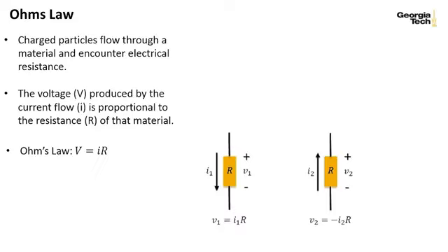So if we have two electrical devices, one with a current I1 flowing from plus to minus V1, then we have V1 equals plus I1R. If you consider the other device, V2, where we have current flowing from minus to plus, V2 equals minus I2R. So the same mnemonic device that we've used all along: whichever sign for the voltage you get to first, you can use that one in your calculation. For V1, the current gets to the plus sign first, so it's a positive current. When calculating V2, the current gets to the minus sign first, so we use a minus current.